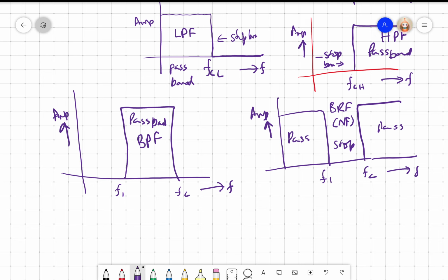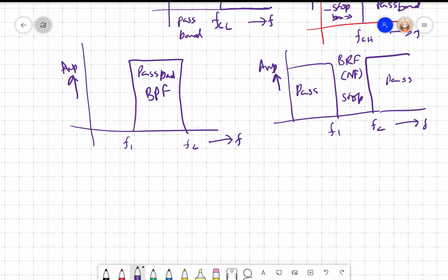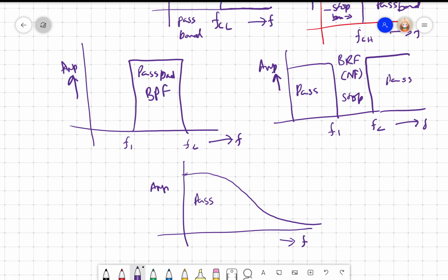Now, this is very easy to understand if you put that. But if I take an actual transducer and get the frequency response, F versus amplitude, I am not going to get something like this, right? It would be some value, almost remains constant and starts reducing and moves to 0 at some time. So here also, I have a set of frequencies which are low enough that can pass, and a set of frequencies that are high enough that is stopped.